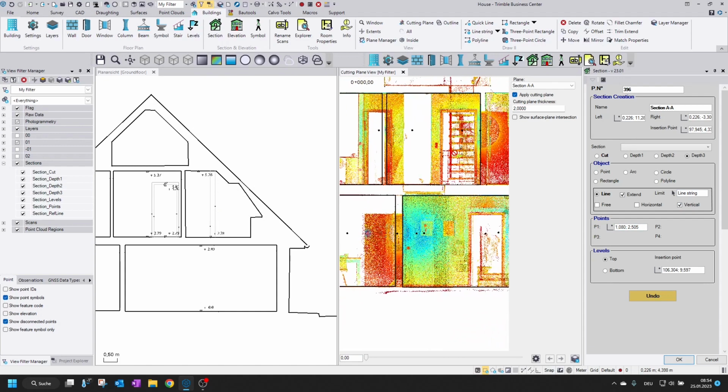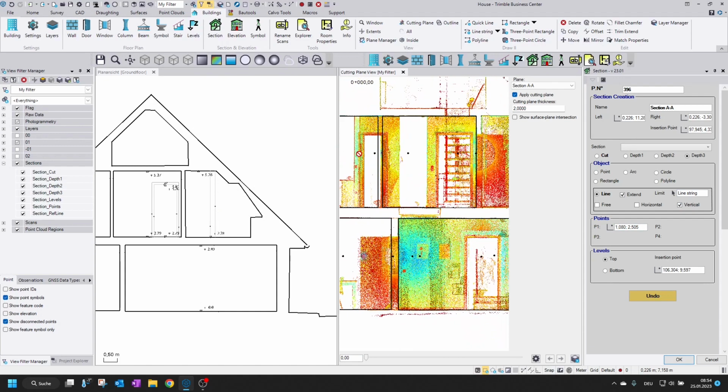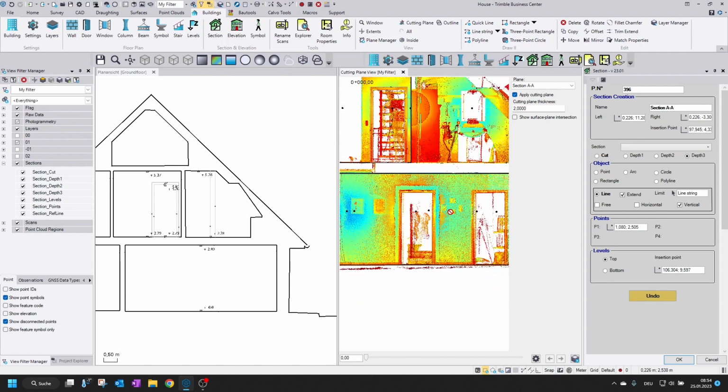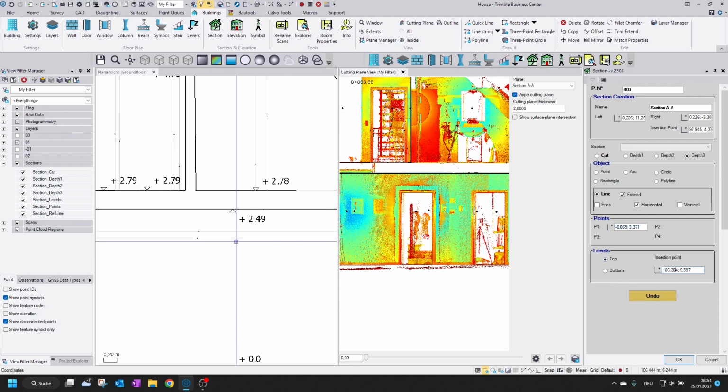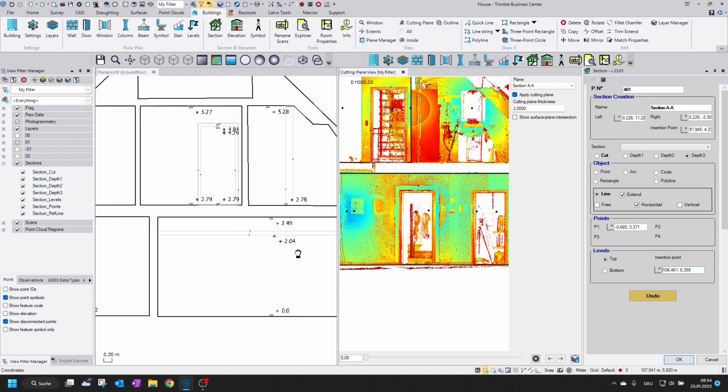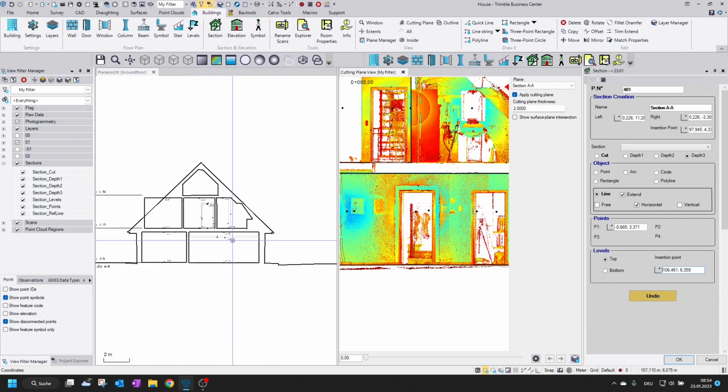And for example, now we have some beam crossing somewhere. So for example here, we say line extend but horizontal, and we pick this polyline, and then as soon as we pick here, you see that we are creating a horizontal line, and it's been extended up to the boundaries. And now we could say bottom or top, sorry, there, so we could annotate this level there.